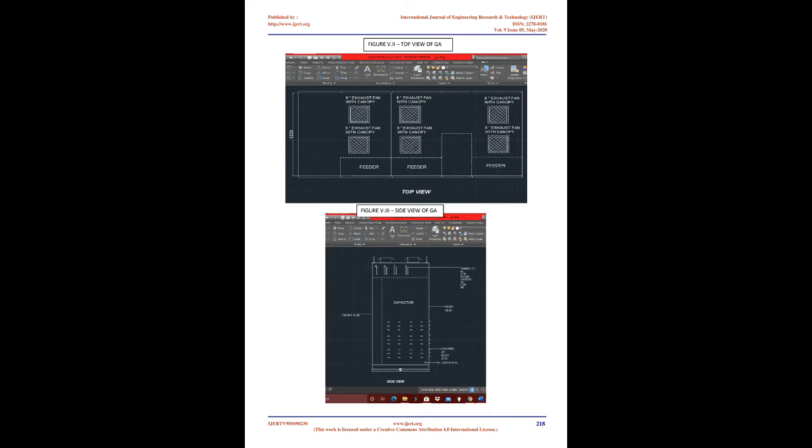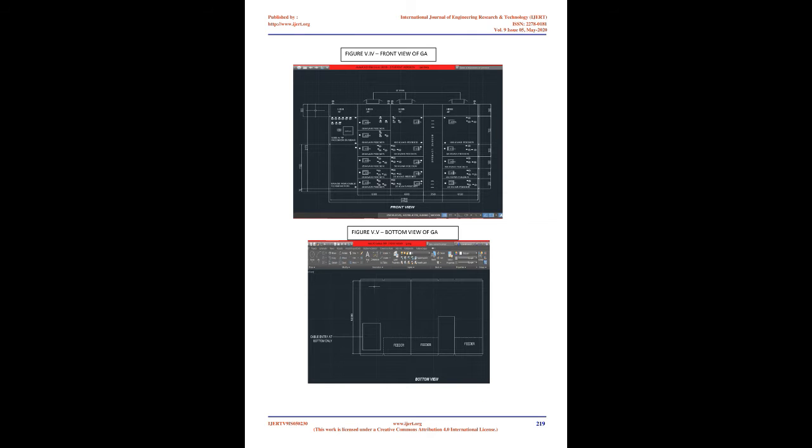In power factor improvement by a synchronous condenser, the three-phase load takes current IL at low lagging power factor cos φL. The synchronous condenser takes a current IM which leads the voltage by an angle φM. The resultant current I is the phasor sum of IM and IL and lags behind the voltage by an angle φ. It is clear that φ is less than φL, so that cos φ is greater than cos φL. Thus the power factor is increased from cos φL to cos φ. Synchronous condensers are generally used at large-scale supply substations for power factor improvement.